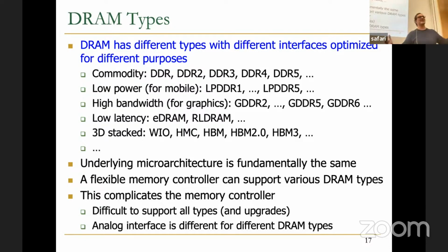So people may say Compute Express Link will have the same latency as today's DRAM. That's, I think, violating the fundamental laws of physics. I don't know how it can be possible. Because you can design a very high bandwidth, low latency interface if you're optimizing that interface to a particular DRAM type on the processor. And also the length of the interconnect is just fundamental, right?